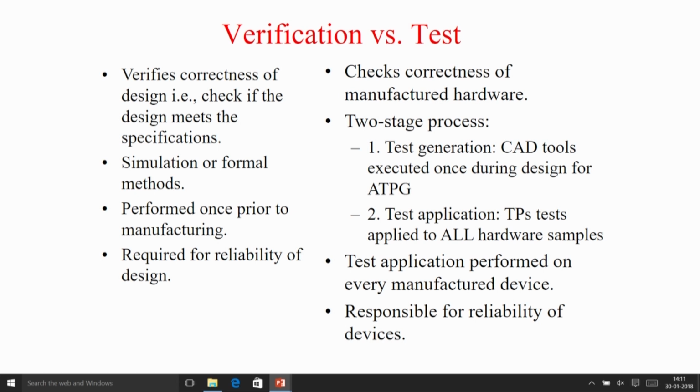You have the devices there, you put some test patterns and you verify and determine whether there is any defect or not. But testing is actually a 2-stage process, as we have already seen. One is test pattern generation or test planning: given a circuit, what are the inputs you have to give, and at what timing you have to give them. All these plannings we saw in the last module are called test planning. That will give you the test patterns, and once the device is fabricated you have to apply those test patterns. So there are 2 cases, one is determining the test patterns and one is the final application. Testing is a club, but practically speaking, quote unquote testing means the patterns are there, the device is there, you physically apply it.